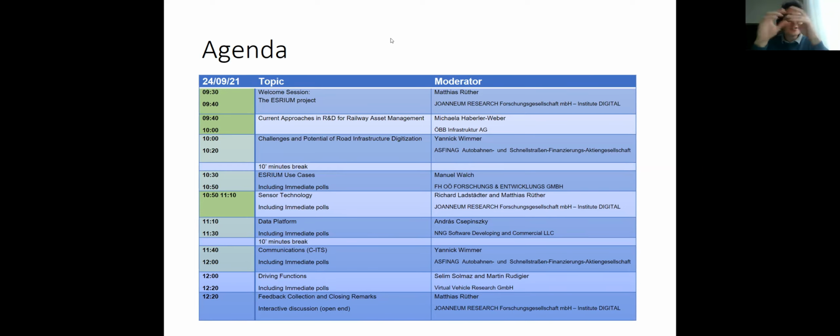Sorry. So first of all, you have to understand that with those roadside units, you don't really need to have full coverage to cover actually what you want to transport to the vehicles, because you can send out, of course, and this is what will happen all the time, some information that is relevant some kilometers down the road. But you receive it already beforehand, and the vehicle has it on board, and it knows, okay, I have to pay attention in maybe 2-3 kilometers. So this is why you don't need really full coverage, because it would be a waste.